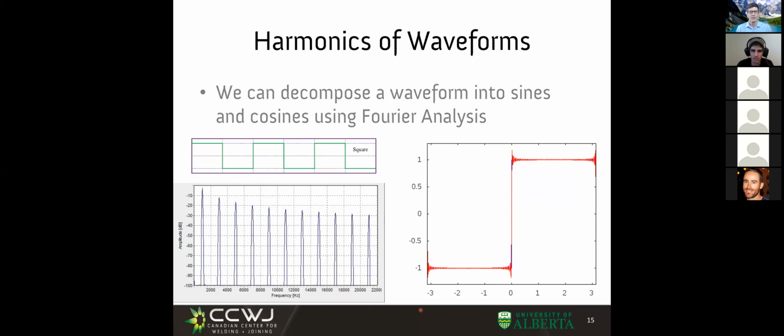That sounds good. So then how do you explain that we can use AC in processes such as MIG or such as TIG, right? In which we don't have an arc stabilizer at all, just the opposite. Argon has a huge ionization potential compared with potassium, right? How can it be? It is because we use square waveforms.